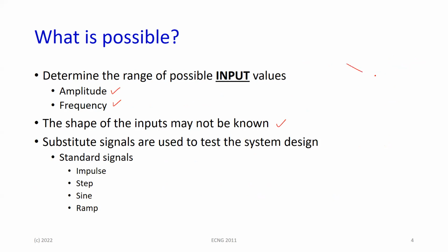So for instance, if you're dealing with an audio amplifier, you can know that the output is going to be, let's say, 10 volts. Right, so it's going to be plus or minus 10 volts. You know that the frequency is 20 to 20 kilohertz. Right? This is going to a loudspeaker, so you know that the impedance of the loudspeaker is, let's say, 16 ohms.